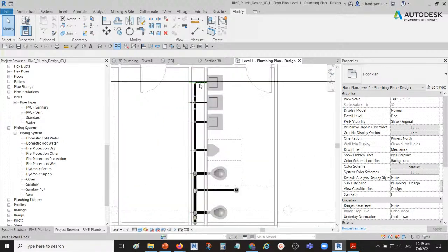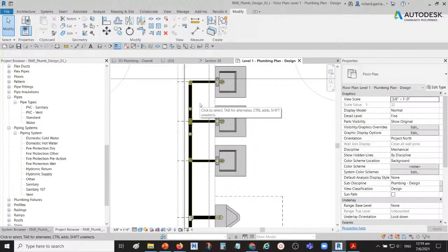We do not simply connect all of that because usually in the developed design, the architect is still changing or replacing the location of your fixtures. They don't want the design, so they keep on changing. Okay, so just remember you also need to ask what the stage of the project is. If it is detailed design, make sure it's detailed already. You connect all the fittings because most likely more than 50% of the design is already complete on the architect side. Okay.